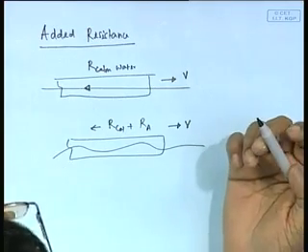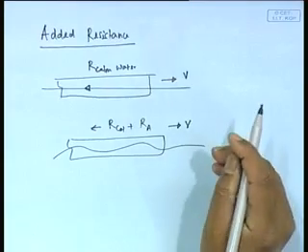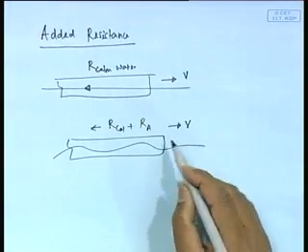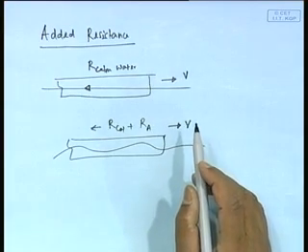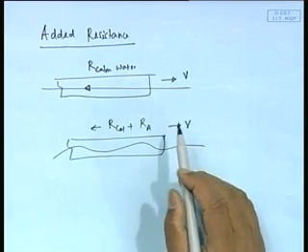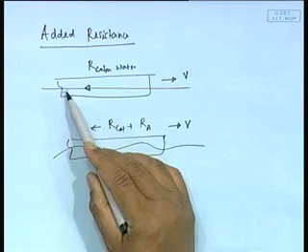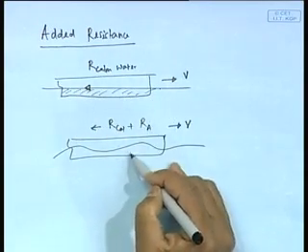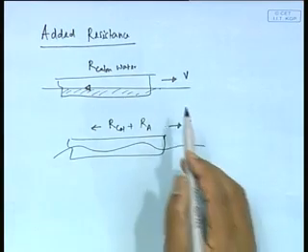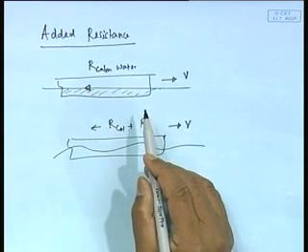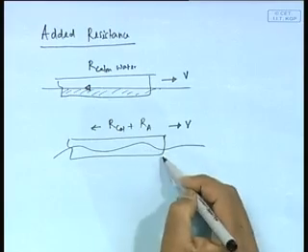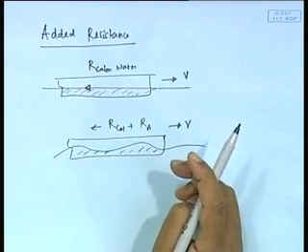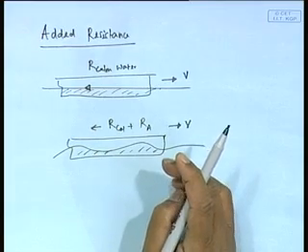Why does it happen? If I ask you this question, what is the physics behind this, what will be the answer? Let me try to understand from you. We have all done a resistance course before. So, we know resistance depends of course on skin friction on this area and also wave making resistance. Now, there will be a temptation for us to say that because it goes on the waves, my underwater part is changing, therefore I will have additional resistance, but that is not fully correct.